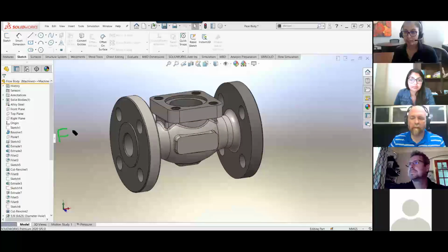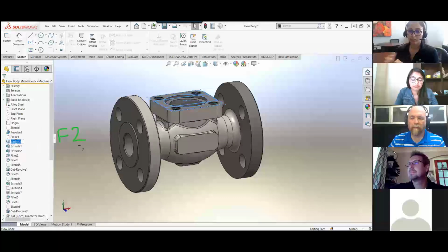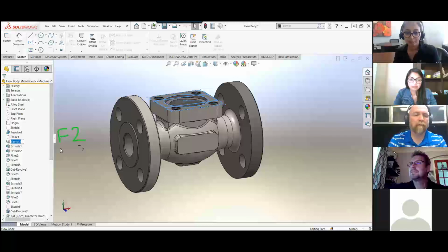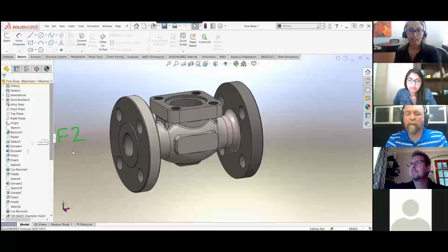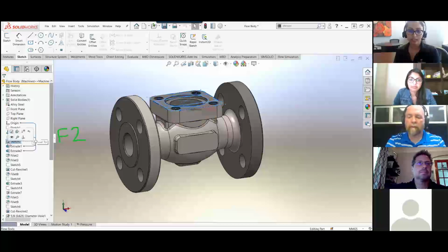I take advantage of some Microsoft functionality. If you click on that sketch and then hit F2 on the keyboard, F2 is edit cell in Excel. So we're just stealing that functionality here in SOLIDWORKS. Now I've certainly met people who are just trying to get access to these icons, and so they're clicking on the text here, but they accidentally cause the text to edit all the time, which is very frustrating to them. Just a little way to train your hand. Train yourself to click on the icons if your intention is to get these icons. If your intention is to edit the text, then that's the only time you should actually click on the text.